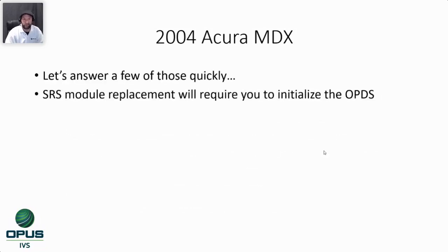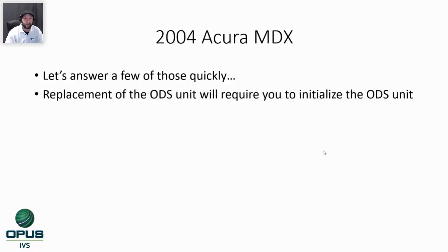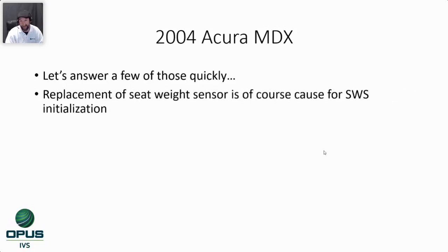So let's answer a couple of them. The SRS module replacement will require you to initialize the OPDS. Replacement of the ODS unit will require you to initialize the ODS unit. Replacement of the seat weight sensor, of course, seat weight sensor initialization.